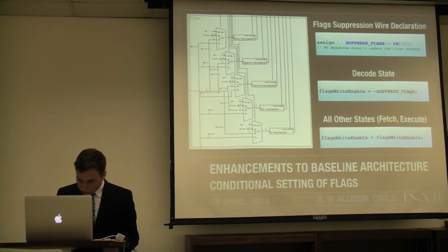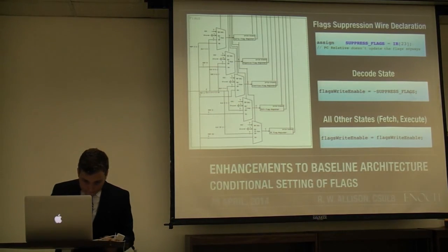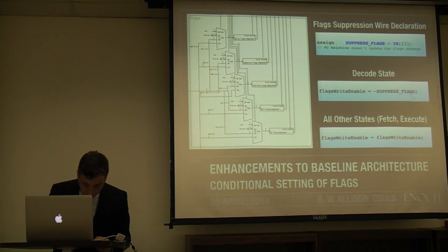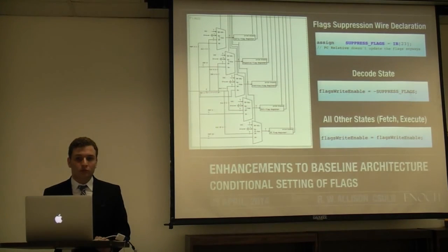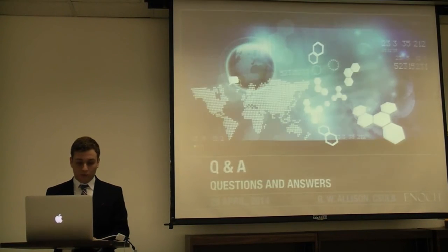If we were to pipeline this in the future, like MIPS, during one time it's taking the PC and adding 4 to it, utilizing the ALU, which is empty during that cycle. But say we want to do something at the same time with our processor in the future. We couldn't really do that if we were using the ALU so much during every instruction.